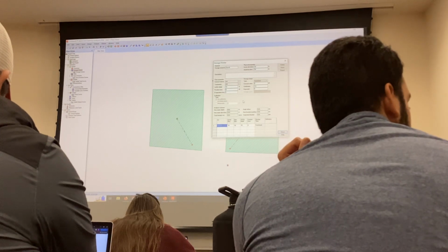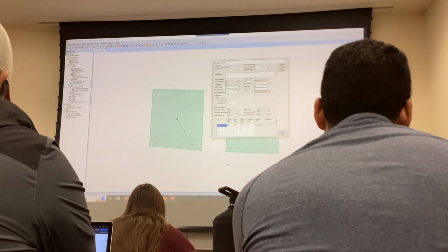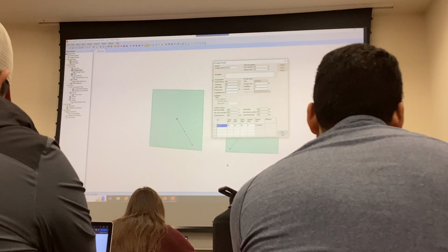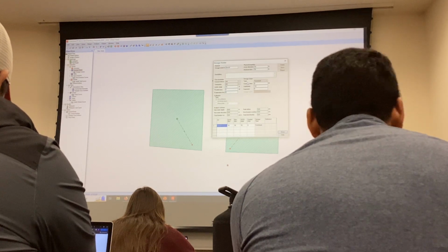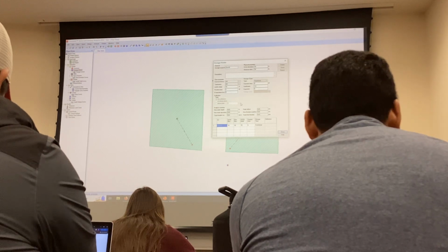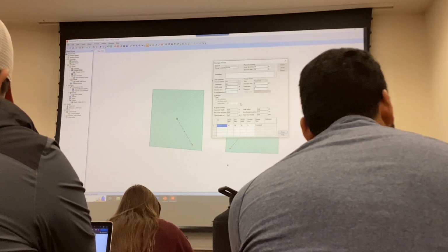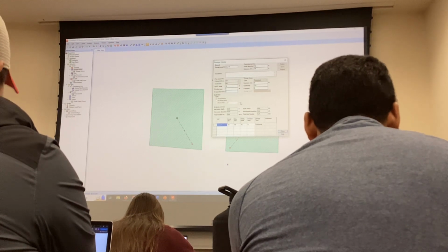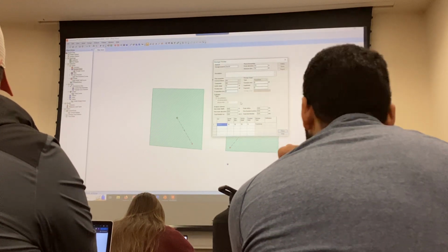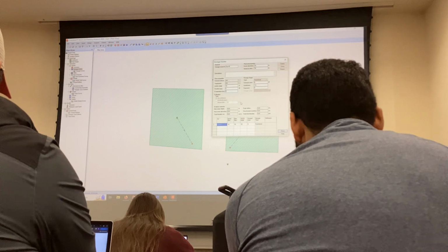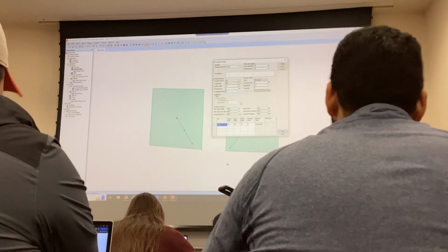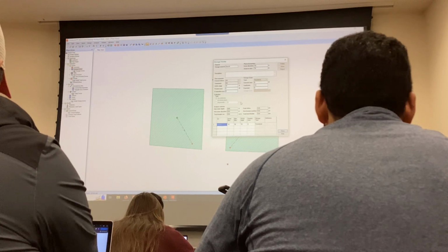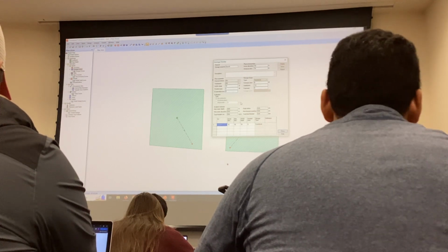Okay, so just assume ponded area is 0 for this purpose, and then what I want to do next is tell the program what my detention basin looks like. The program doesn't know what shape your detention basin is, or how large the area is of every layer. It knows how deep, but not the shape. So now's the time where we specify this into your SSA.